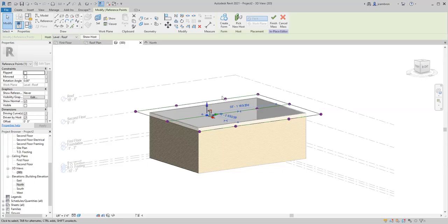Okay, that's important because it's difficult to get a sense of depth in a 3D model, because we lose the sense of depth. So it might look like I'm going up, but it might actually, in fact, be going backwards, right? Because of that, Revit gives us these guides, these arrows, so that we can just click on one and drag, and we can ensure that it's moving up or down, or to the green or to the right. I'm sorry, to the green or to the red.